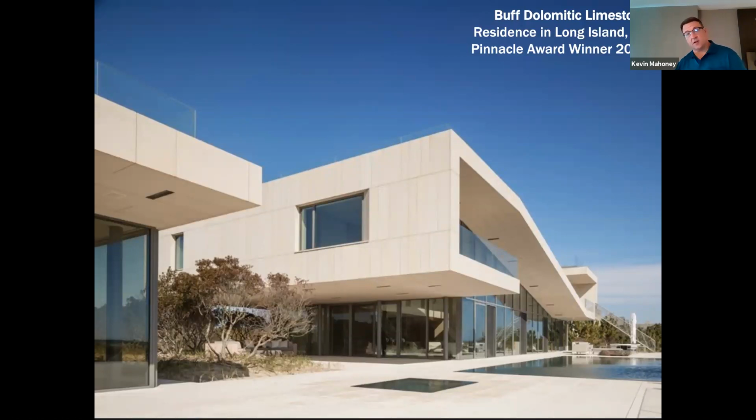It works exteriorly, and understanding what the limestone's flexural strength is, sometimes limestone and where it's harvested from, can lead us to how we're going to hang that, whether it's kerfs or dowels and things like that. So if you're an engineer on the call, it's important to understand that limestone has the proper hanging based on the composition of that stone. And it can be accomplished. You just have to find out where that stone came from and how it's going to perform.